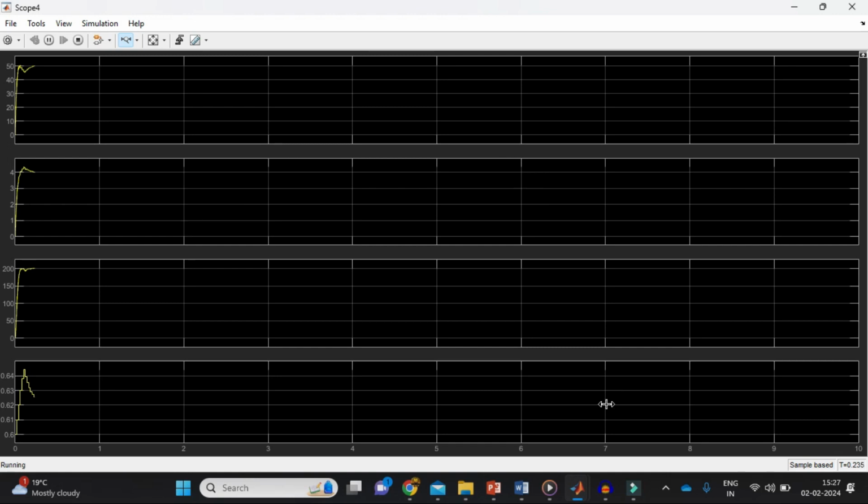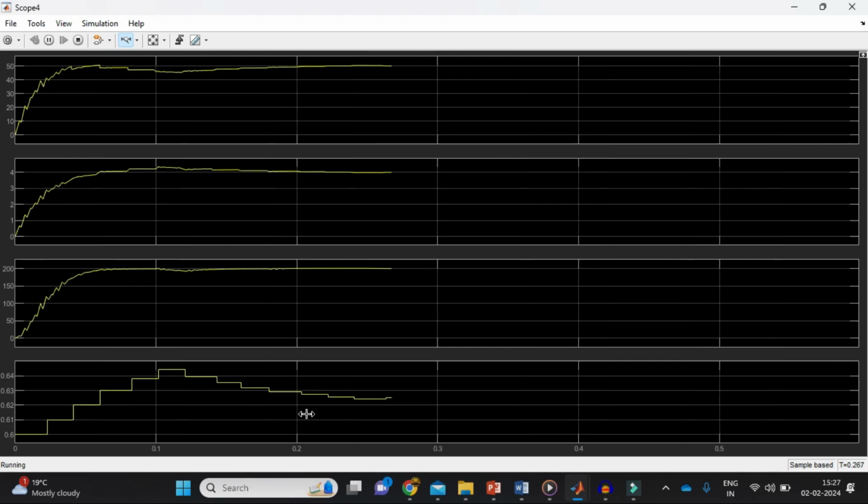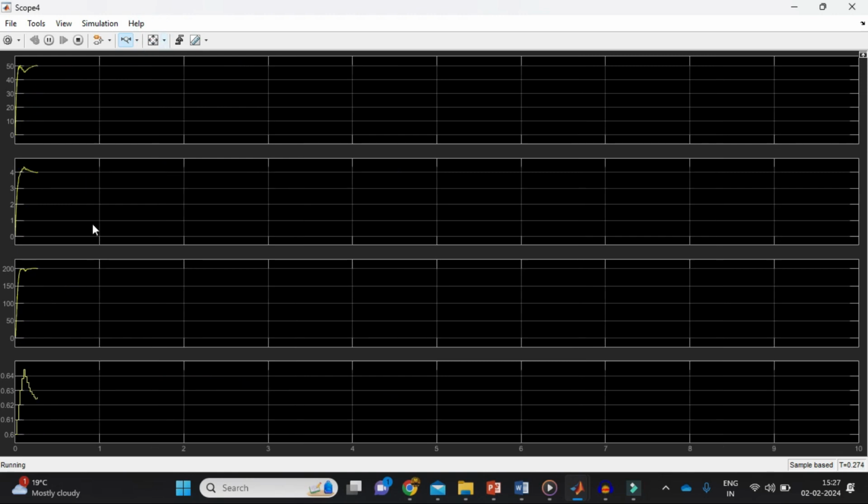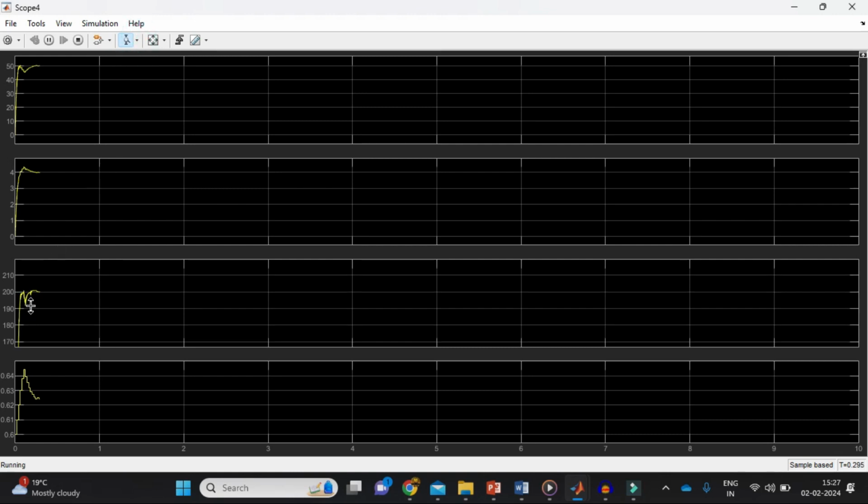But when I consider from here, when it starts from the right hand side, it oscillates at higher value and then it continuously decreases, and when it reaches the maximum point, it reduces. See, it reduces here. It reduces, right? So why am I using it in this fashion? Because it will create lesser steady state oscillations in this case. See, when I talk about the oscillations, very few oscillations are coming, and the tracking time for reaching the maximum power point is also reduced by using this technique. So that's why I'm using this technique.